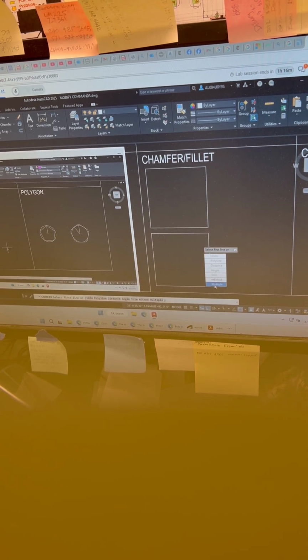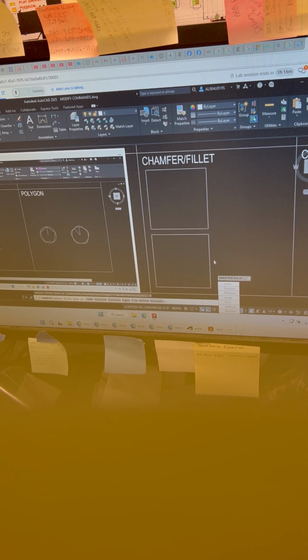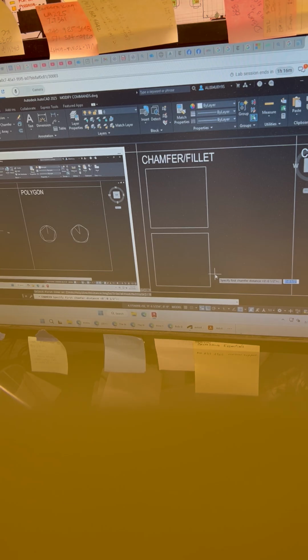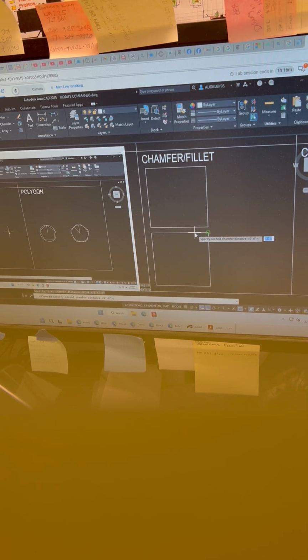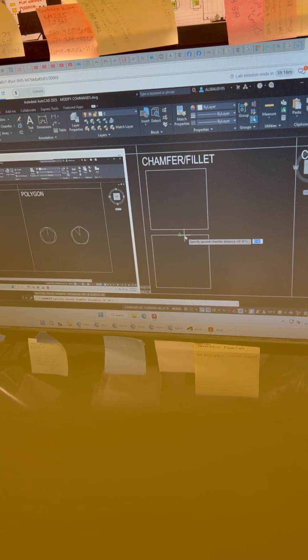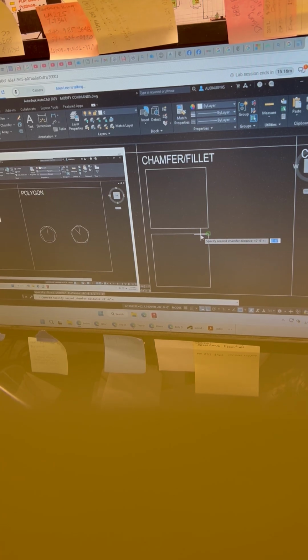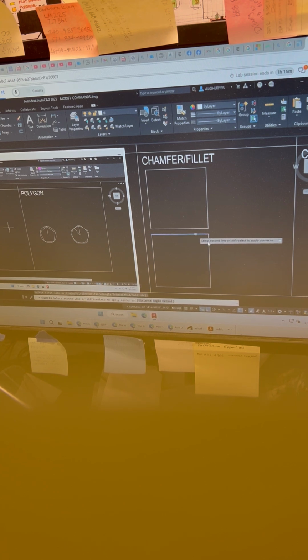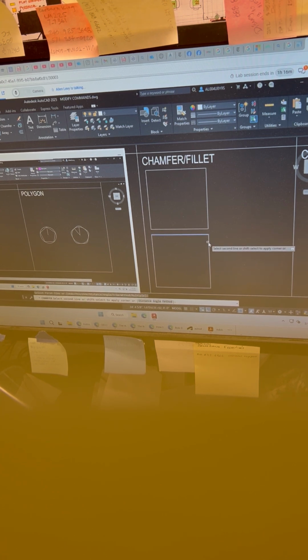All right. I want you to do something for me. I want you to select both of these polylines, and I want you to explode them. Once they're exploded, here's what I'd like you to do.